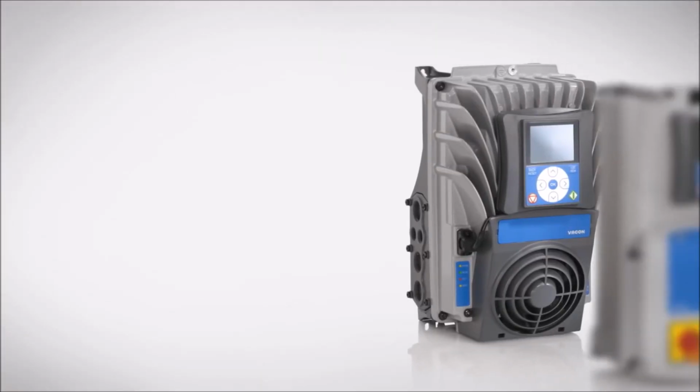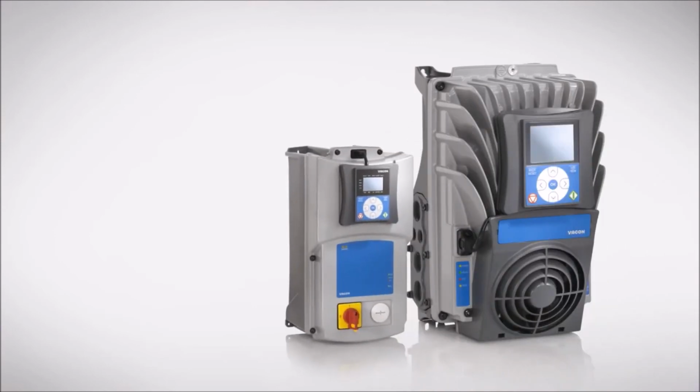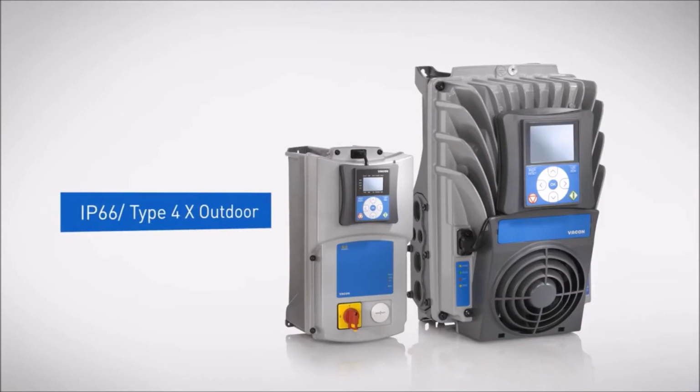VACON 100X and VACON 20X are two decentralized drives that come with IP66 Type 4X outdoor enclosures. These enclosures provide full protection from external hazards, allowing the drives to be located as close to the motor as necessary. This means that customers don't have to worry about spending extra money on shielded cabling.